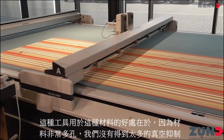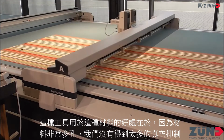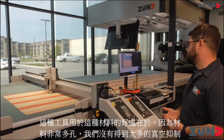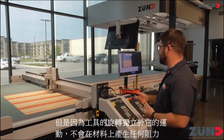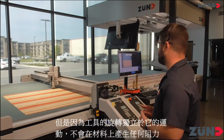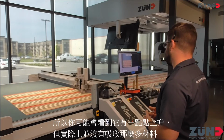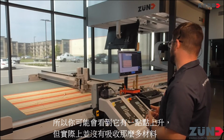What's nice about this material is that with this tool, because the material is very porous, we're not getting much vacuum hold down. And in fact, the vacuum is barely on right now. But because the tool is spinning independently of its movement, it's not creating any drag force across the material. So you might be seeing it pick up a little bit, but it's really not picking the material up much at all.